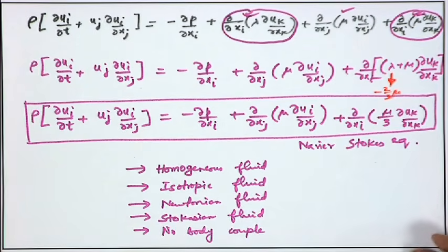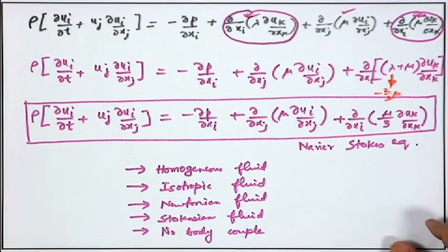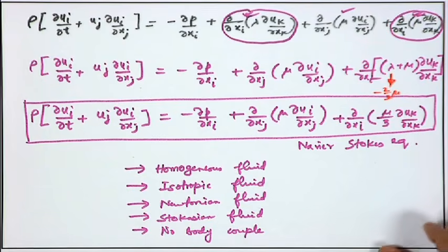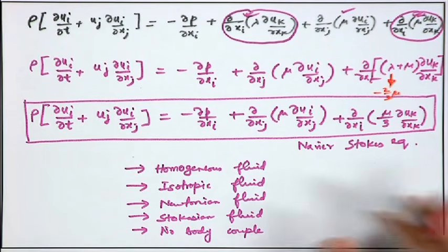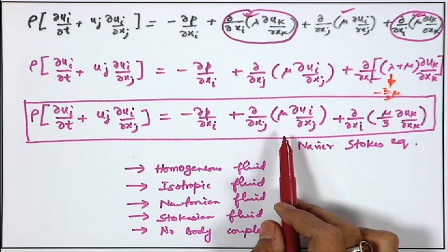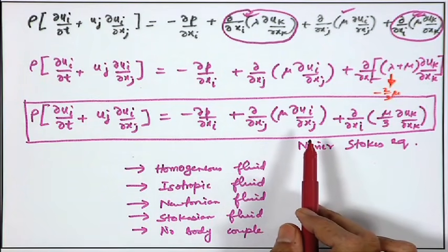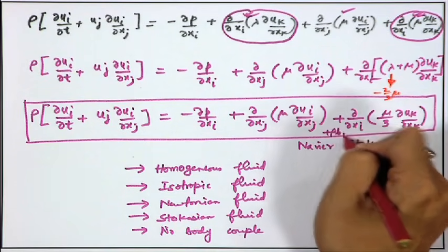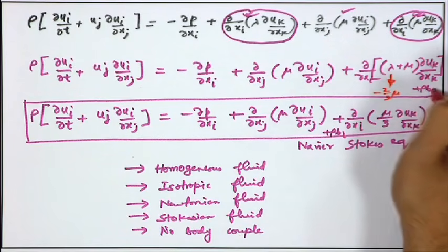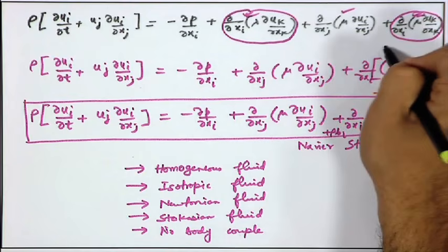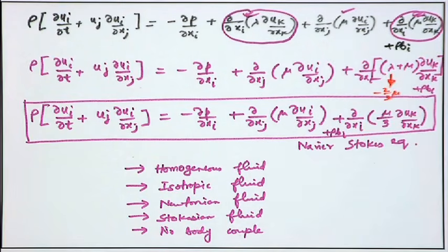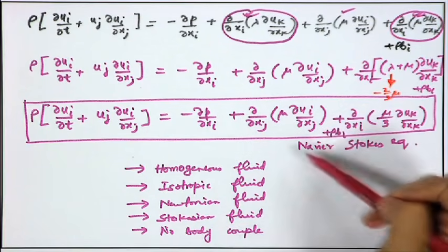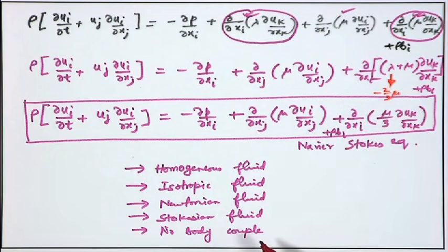See, very often for the Navier-Stokes equation we say momentum equation or momentum conservation equation. We do not say linear or angular, because the fact that we have used tau ij is equal to tau ji. Oh, there is a body force in this equation which we have not written, rho bi, yes, plus rho bi. So, add the body force in all the equations. So, we have assumed that tau ij is equal to tau ji. So, that is true if there is no body couple.